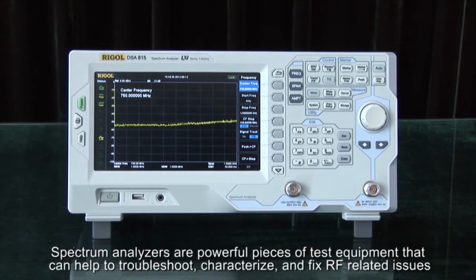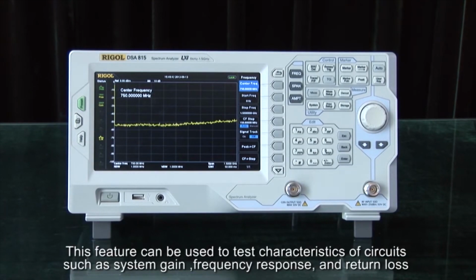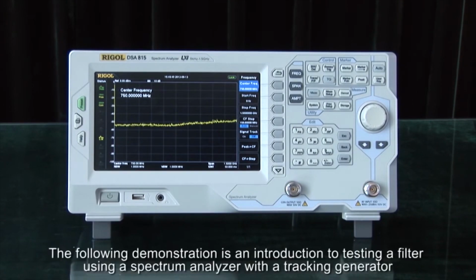Spectrum analyzers are powerful pieces of test equipment that can help to troubleshoot, characterize, and fix RF-related issues. Instruments equipped with a tracking generator also have the added benefit of being used as a scalar network analyzer. This feature can be used to test characteristics of circuits such as system gain, frequency response, and return loss. The following demonstration is an introduction to testing a filter using a spectrum analyzer with a tracking generator.